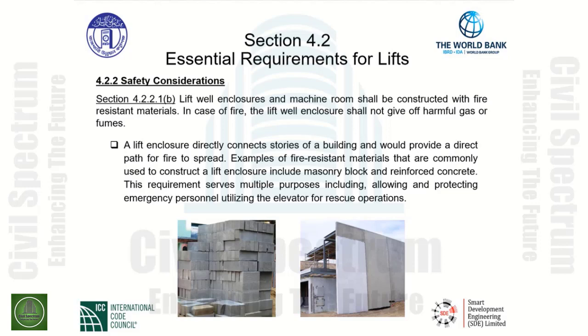A lift enclosure directly connects stories of a building and would provide a direct path for fire to spread. That's why we have this section here to be made of fire-resistant materials when it comes to lift well enclosures and machine rooms.